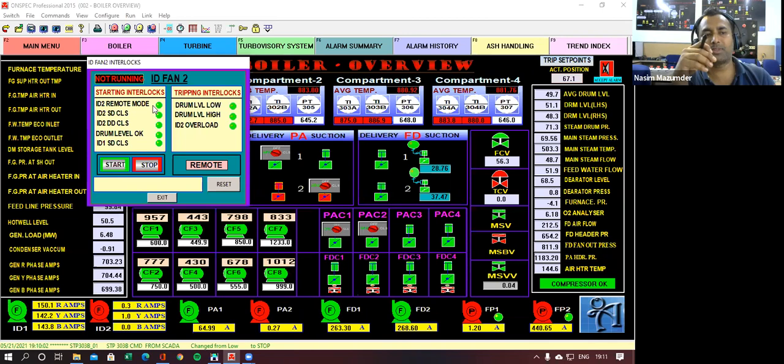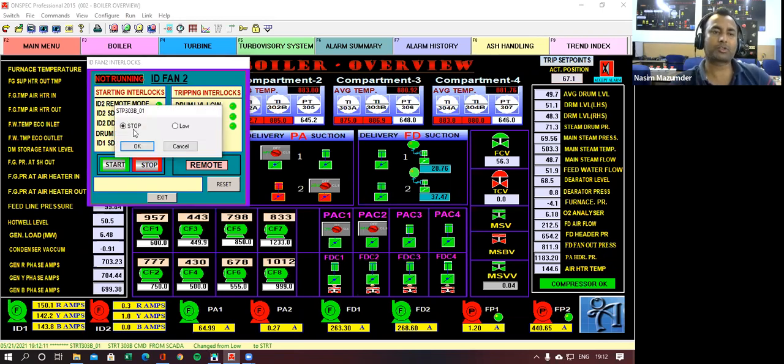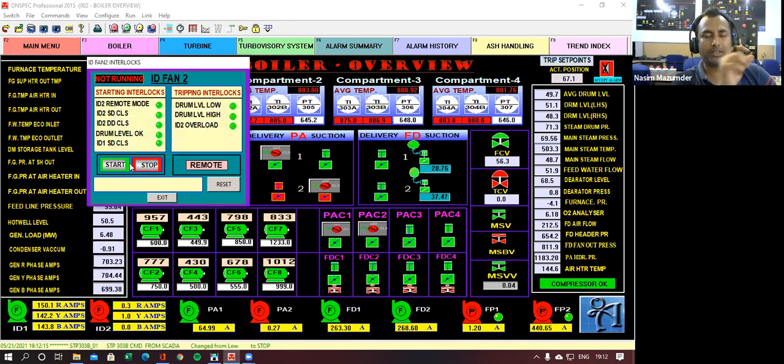Now, today we will be looking at how these are turning red or green. So, so far you have understood this start and stop command, isn't it? How the start command is going, how the stop command is going. These are communicating through hardwire, and the command is going from particular channels. Now we try to find out how these indicators are becoming red or green.